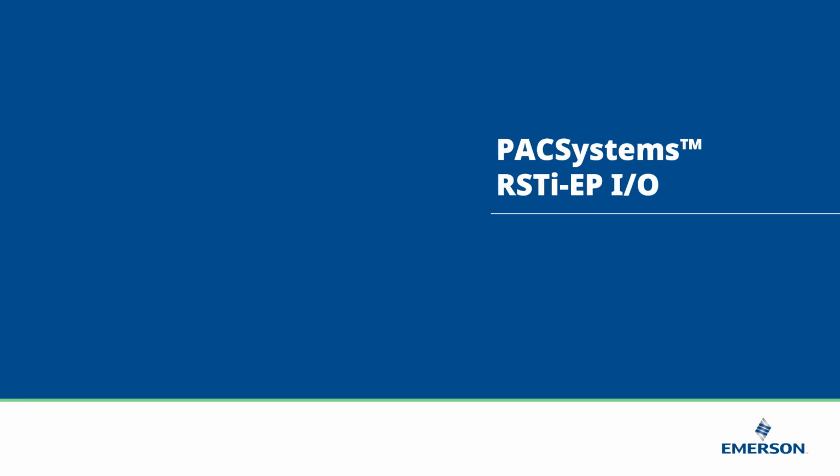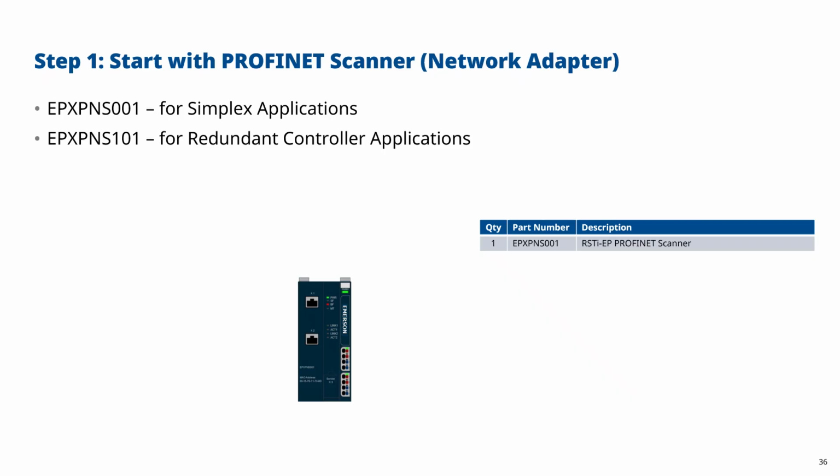So we'll start with the PACSystems RSTi-EP I/O, and this is intended to be low cost slice I/O that takes up minimal panel space, but still gives you some very good I/O capabilities. So the configuration process is similar to the CP200 range, except instead of having a CPU, we now start with a PROFINET scanner or a network adapter.